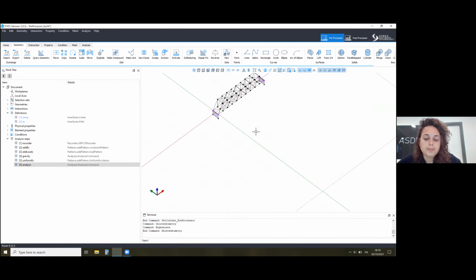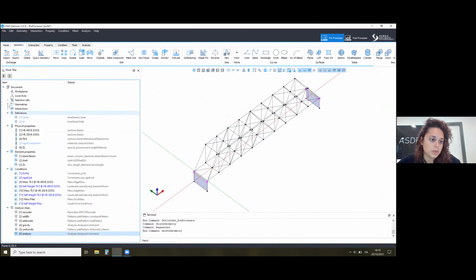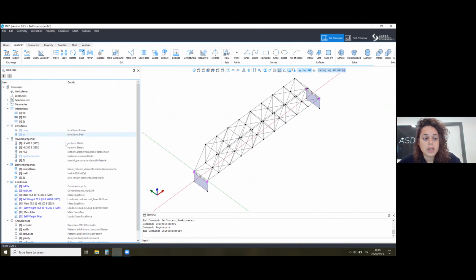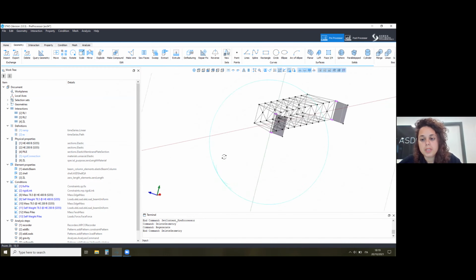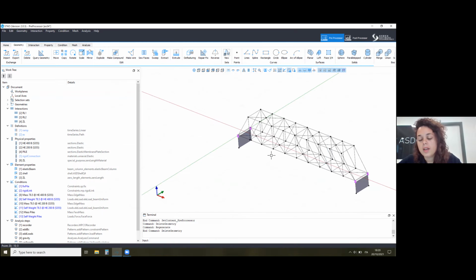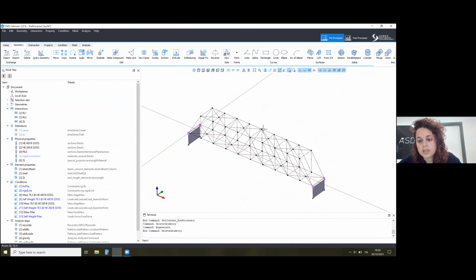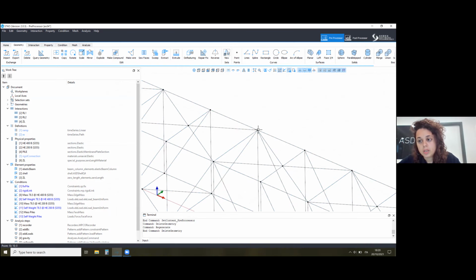So one thing that can be useful, I imagine, because this is what the application has been until now, is that for now, all the beams that we modeled, the bracing, the horizontal deck, the lower and superior deck, the vertical elements, everything is connected in a rigid way because it's merged, it's a wire. But what if you want to release some of the degrees of freedom in these nodes? How do you do it?